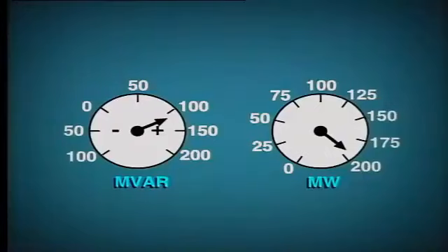Well, the problem is that even though increased energy input is not required, increased current still flows through the generator windings and through the power system. The result of this is that we could easily overheat the generator windings if we had a high megawatt output plus a high megavar output. Definite limitations are placed upon the combined total output of megawatts and megavars.